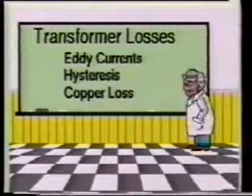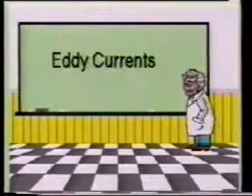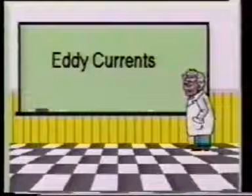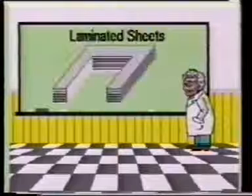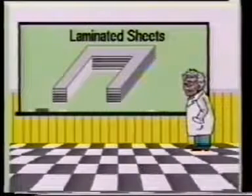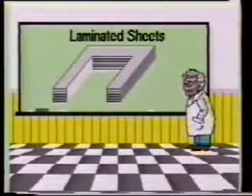Transformer power losses are caused by one of three things: eddy currents, hysteresis, or copper loss. Eddy currents are losses induced by circulating currents within the core of the transformer. To overcome this loss, the core is made from thin laminated sheets of iron or steel, which are coated with an insulating material such as plastic, then stacked together.